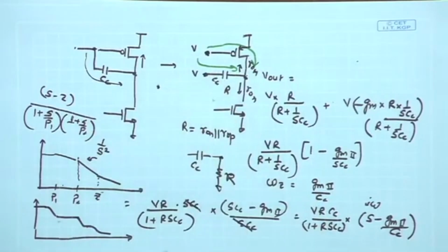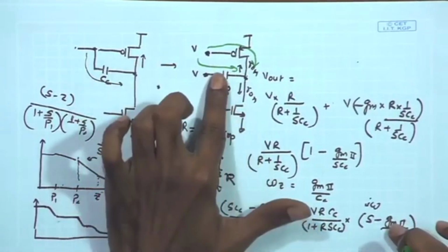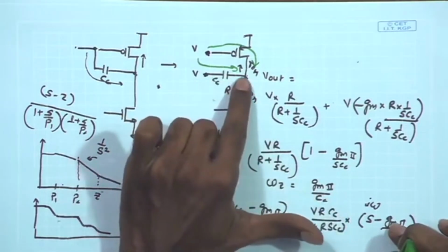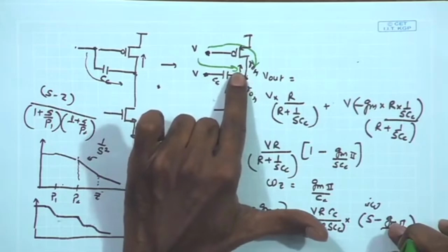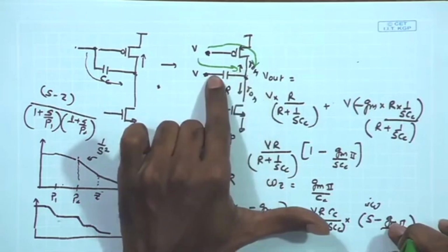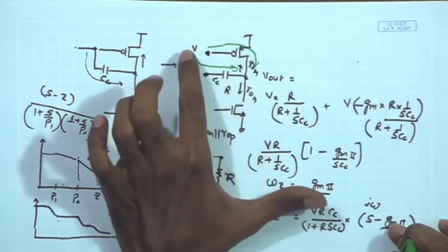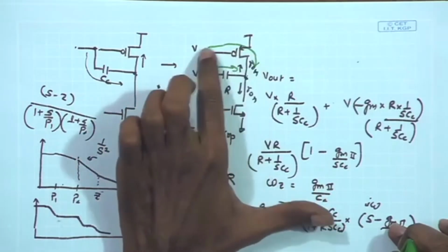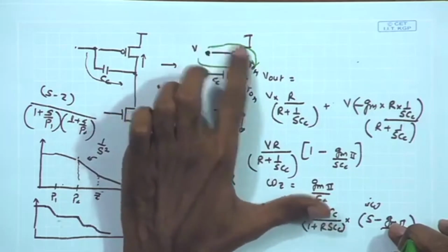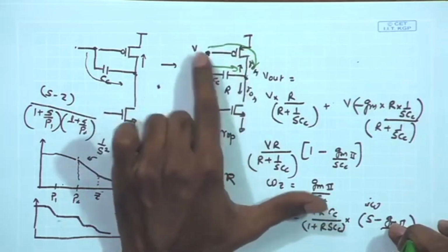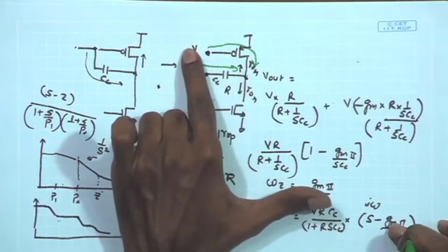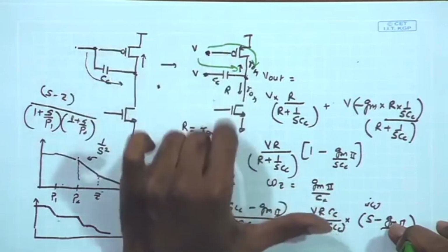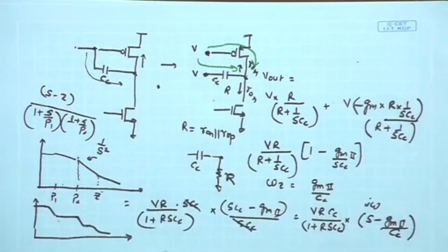That is one strategy, one possible scheme used to compensate this kind of circuit, and in order to do that we can think of inserting some component over here which can block the second path. So, basically we want to eliminate the signal transmission from the input to the output through one of the path. Of course, this is not that path because this is the amplification path, we do not want to disturb this path, but this is an undesirable path through which the signal is propagating from the input of the second stage to the output of the second stage, and if we can block that, then we can succeed in our stabilization.